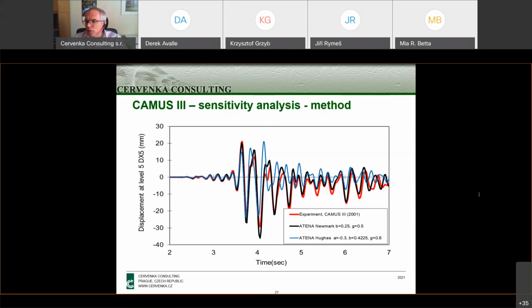This is the other question. Perhaps it is possible to apply the ground motion components by different load cases. I'm not sure how this is meant, but yes, you can define any load history you want. You can define various load cases and then combine them together for different ground motions.